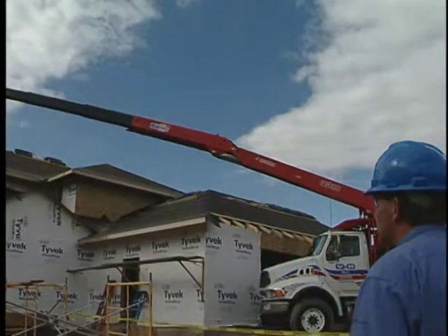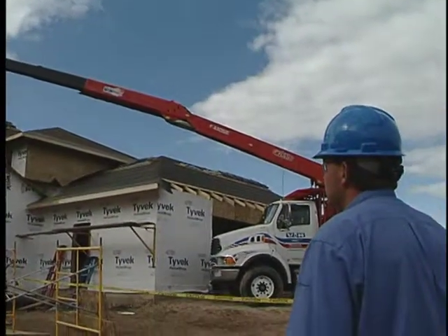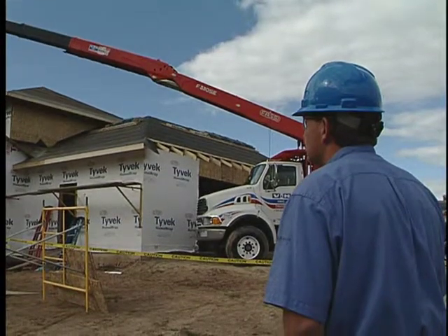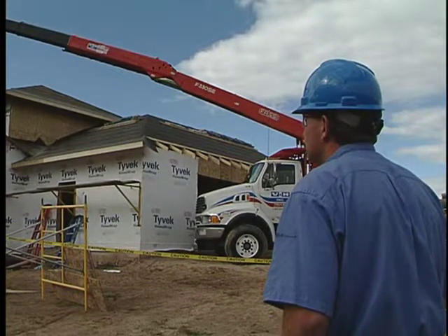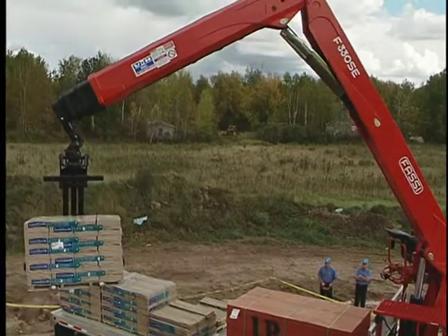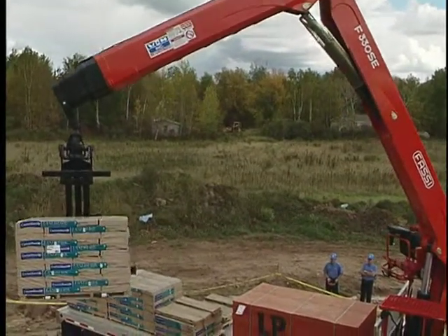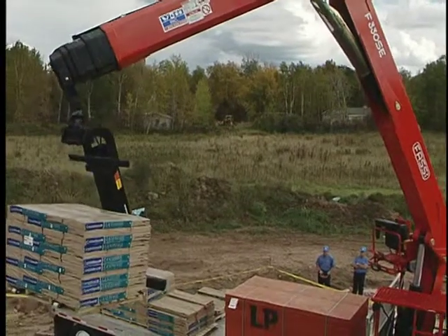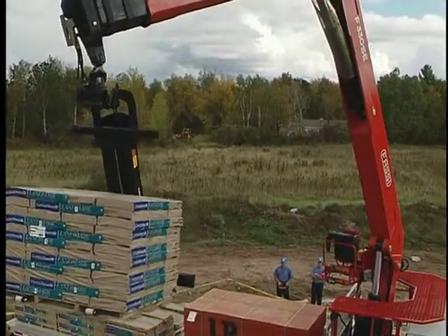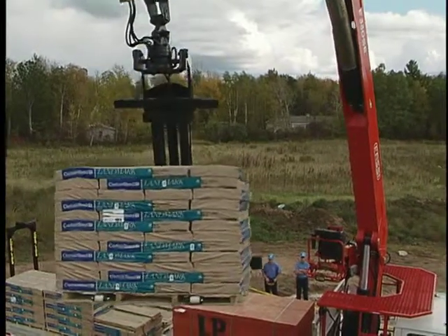The overload shutdown system senses stress on extension, inner and outer booms. It activates a temporary shutdown in overload situations. The overstress system on the model shown provides automatic shutdown at overload. On some models, the system offers diagnostic capabilities and retains performance history.